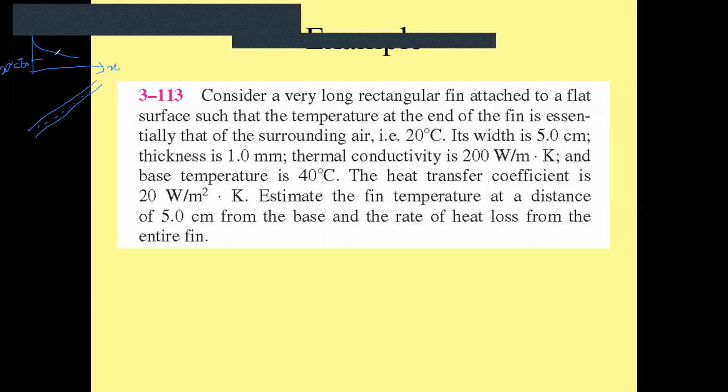It's given here the width and the thickness, the dimensions of the fin, and then the properties of the fin and the base temperature. So this is at the beginning here, at the base temperature. Estimate the fin temperature at a distance of 5 centimeters.